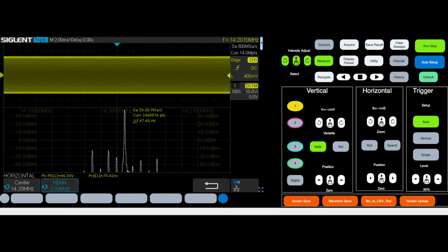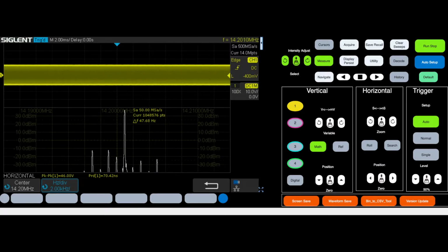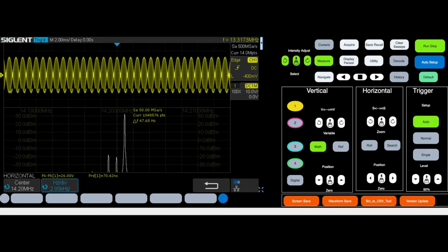If we want to measure a two-tone measurement, we need to make some changes to what we're transmitting. Our levels for a two-tone measurement are typically 1/2 the peak amplitude levels, because that's the way the measurement is specified in the American Radio Relay League method of measuring. We need to generate two tones, not just one, and they can't be harmonically related. So we're going to set a 700 hertz tone and then add a 1900 hertz tone at the same level.